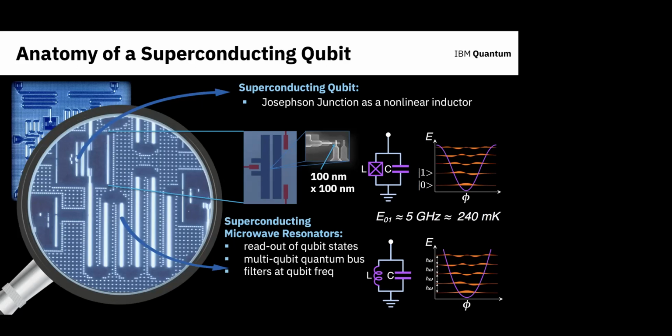Another aspect is the ease of fabrication. Dealing with metals is actually pretty easy, but high temperature superconductors are typically made out of ceramic oxides, which are much more difficult to pattern and deal with than metals. But you do always have to start with essentially a high quality metallic film, and then you'd be able to grow a controllable oxide on it that doesn't have that many defects as well. So great question. Okay, thank you.